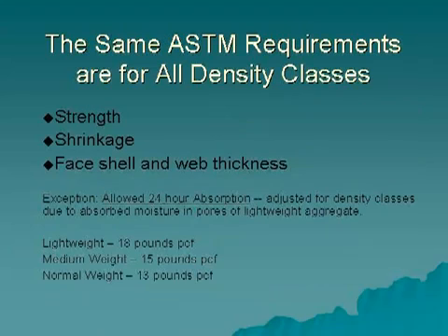Absorption describes the amount of water concrete can hold when saturated and is expressed as pounds per cubic foot. ASTM C90 provides for 3 different absorption limitations for the 3 classes of concrete density. This is a laboratory test as determined by ASTM C140. 3 sample units are oven dried and then subjected to total immersion in water for a period of 24 hours.